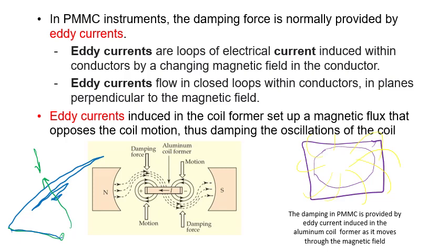To avoid this, this is going to be minimized by the presence of eddy current, so it's going to look like this. If it's at this position and I want it to come here, it's going to start and come. I mean, it's going to be a very short oscillation. It will start, exceed the position, then come back and finish. That's it. So this is going to be faster in terms of getting the right measurement.